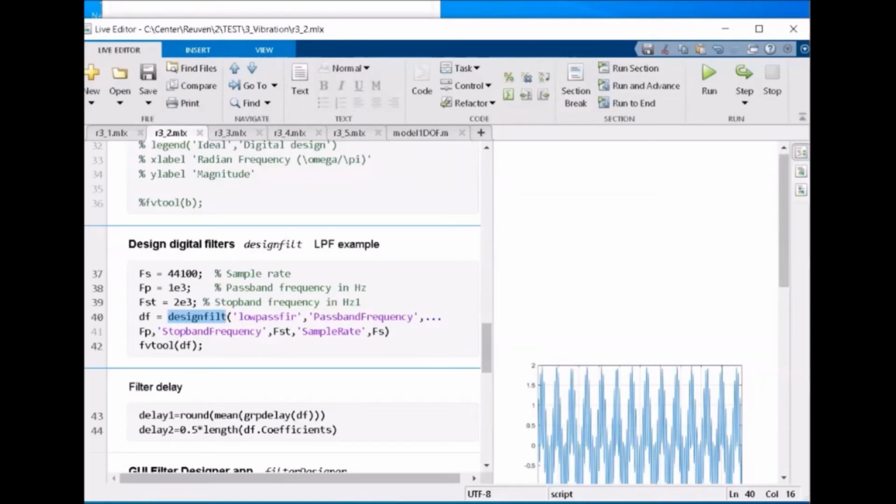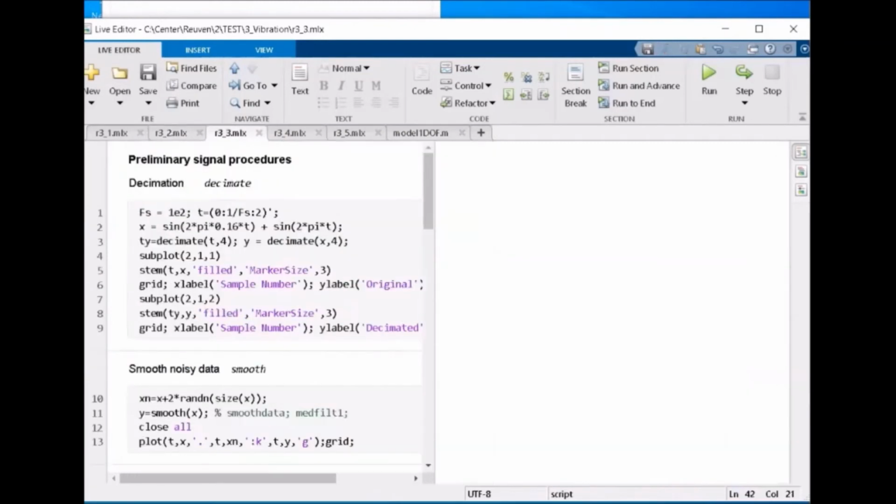When we plot num as a graph, we'll see the impulse characteristic. The filter physically is just the impulse characteristics. For a low pass filter, it looks like a decaying one degree of freedom vibration system. It starts from 1 and goes to 0 with oscillation. So it is a vector. Yeah, it's just impulse characteristics. Okay.